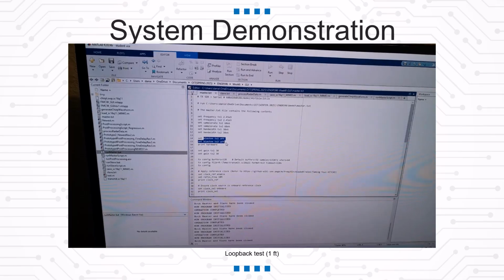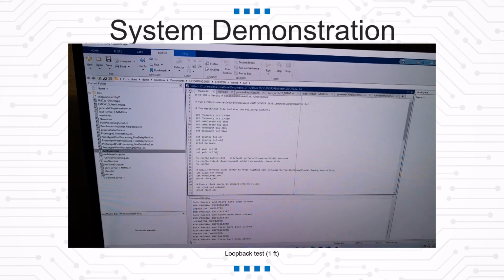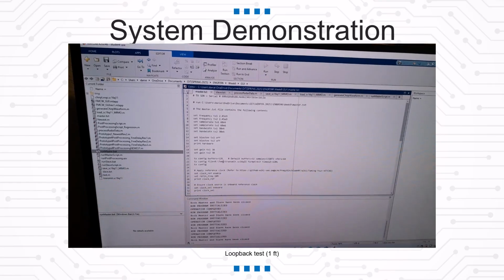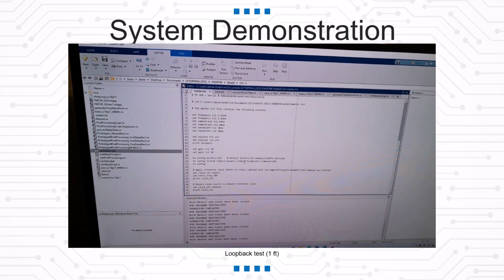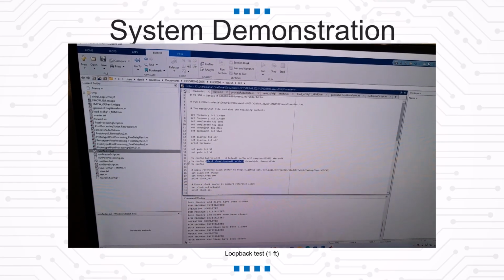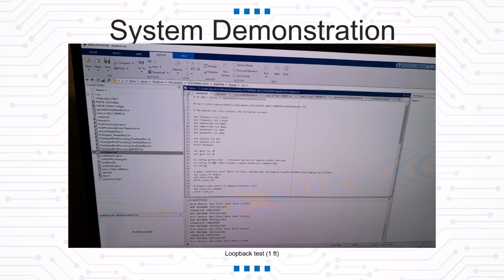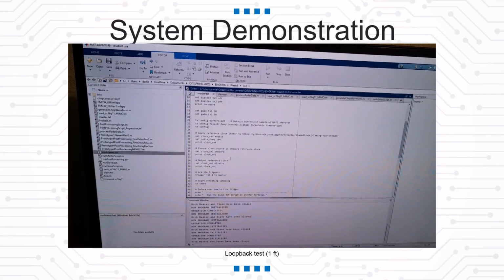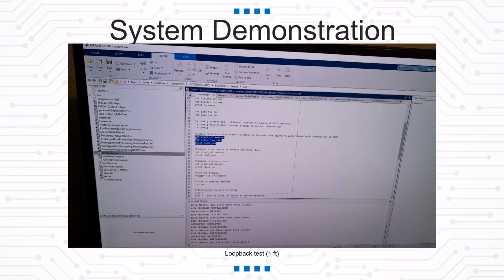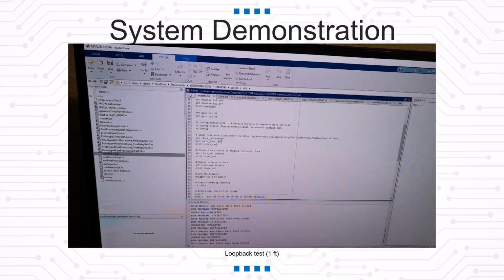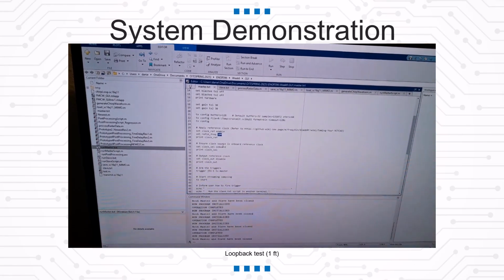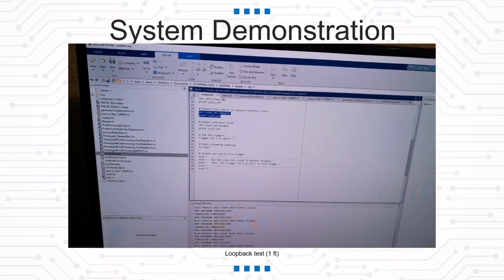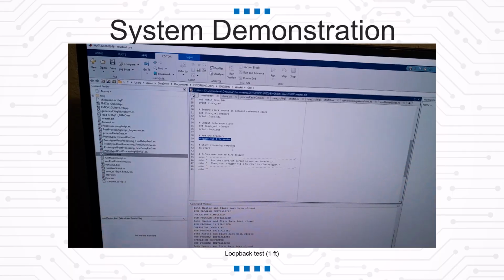It sets the bias Ts, which right now are off. We can set the gain. We configure where the file is coming from. The file we're using is a transmit file, which is saved in digital RAM. And then we apply the 10 megahertz reference clock, and we're using an onboard clock. And then it arms the trigger.